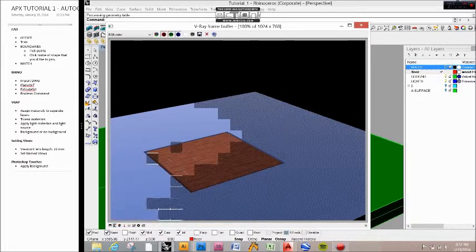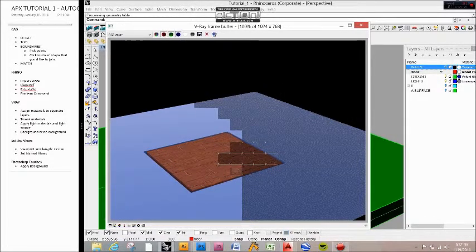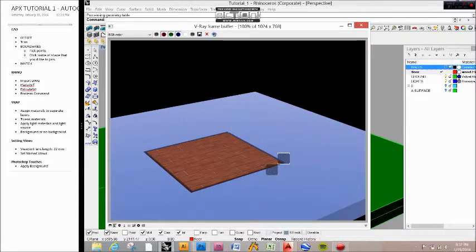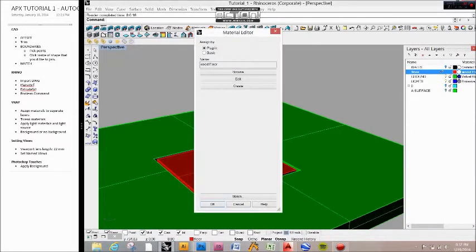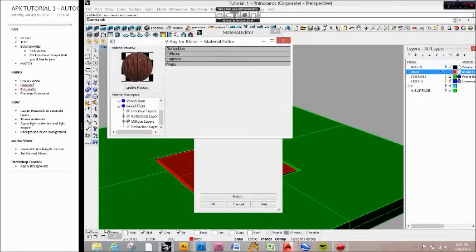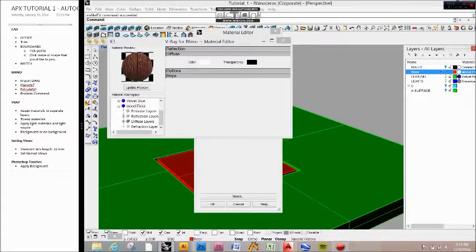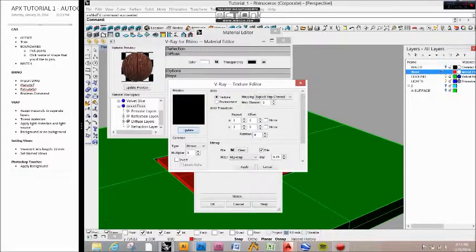like right now in the scale of this thing, these planks are huge, and I don't want them going in that direction. I want them at 90 degrees, turn them, do whatever. I want them at an angle. You can do all sorts of things in V-Ray. You can hit edit, and in the fuse, you can hit this M button right here, and tell it, I don't want it going this direction, I want it going the other way. So the grain suddenly turns from north to south to east to west, basically.